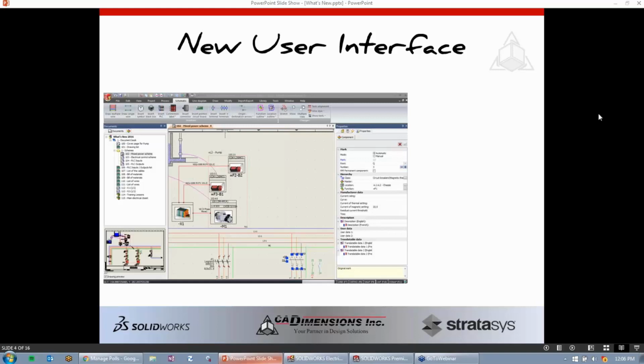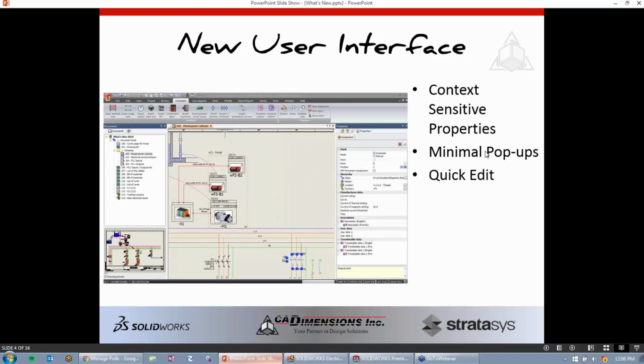So we'll start with our new user interface, which now gives us some context-sensitive properties, which is going to minimize the number of pop-ups that we're used to seeing. So the current process now is to right-click on an object or right-click on a component, go to the symbol or component properties, click on a tab, try to change the manufacturer, try to change some of the properties of that component. We've added a right side panel where we can quickly access all those attributes.